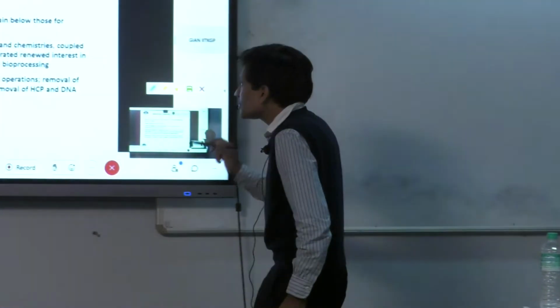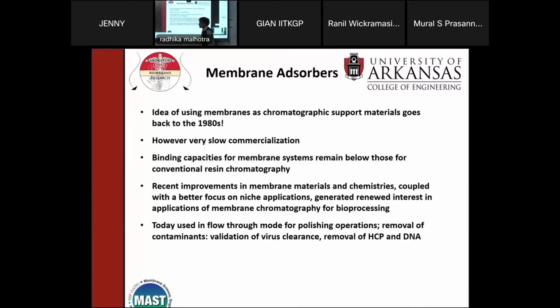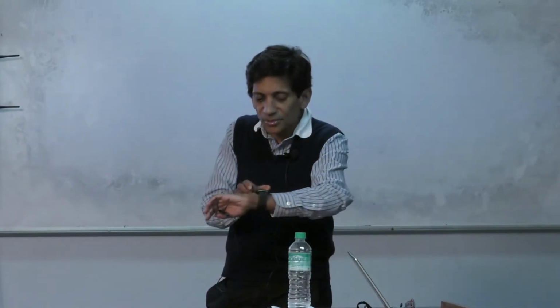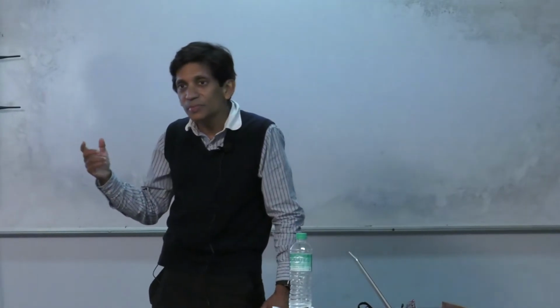And so the niche application is used in what they call flow-through mode. So usually we bind what we want, right? We let all the contaminants go through, we elute our product. That's fine, but there's a problem there if in fact you're capacity limited, because then you might have a high concentration of your product and you can't bind it effectively, you need too much resin, right, or too many membranes. But what we want to do here is actually bind the contaminants. So we don't bind the product.